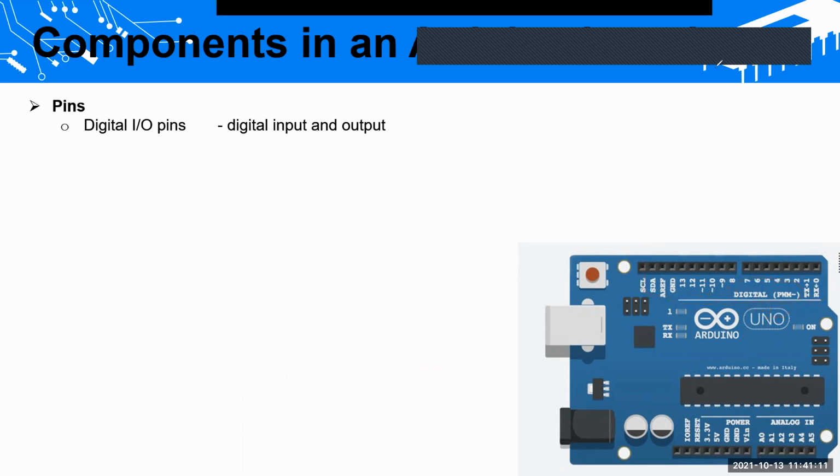Back to this slide, we have digital pins. IO means input and output. You can either use digital pins as input, where you insert certain voltages, or take certain voltages out. They can work as digital inputs and outputs. Then, on these digital pins, some pins work as PWMs, meaning pins that give middle voltages. This dash is on pins 9, 10, 11.